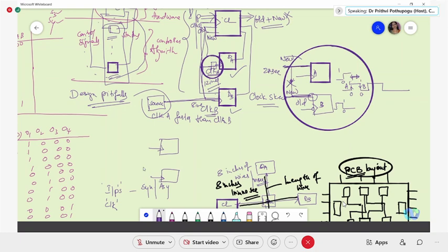How the clock skew gets generated, for that we took clock A and clock B isolated. But it should not be isolated. The source should be common to all the components in that single design. This is the system clock. The meaning of that is it is the clock that is common to all the system components. In synchronous designs, something connected to the system clock means it is common to all the components in the design.